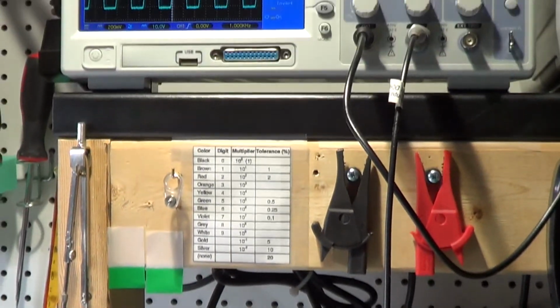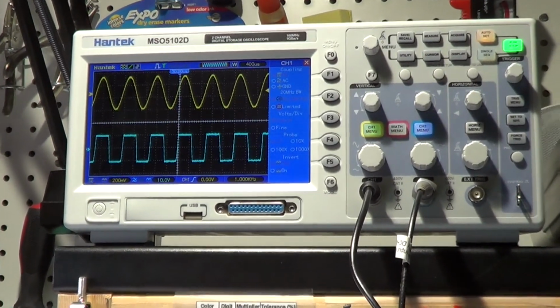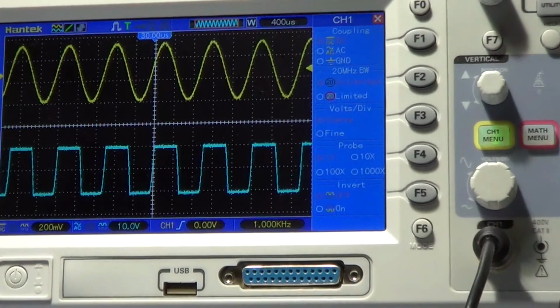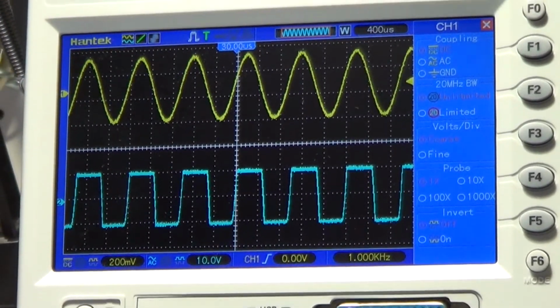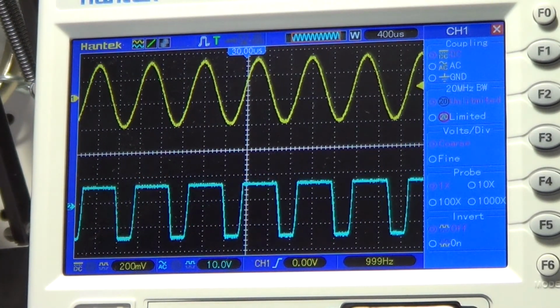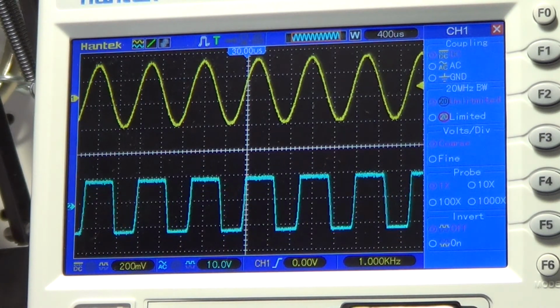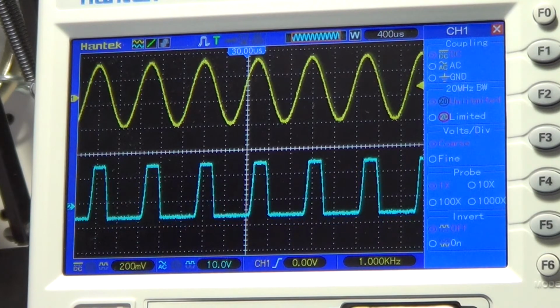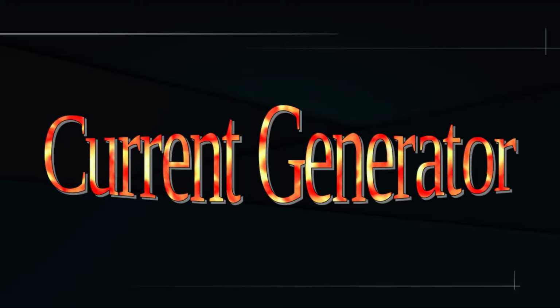You can see that the op-amp jumps from positive to negative voltage depending on the level of the input signal. And since I have the reference voltage to 0, the output goes high on the positive part of the sine wave and negative otherwise. But now, if I change the reference voltage, you can see that the amount of input signal higher than that becomes smaller or higher, and so the length of the ones and zeros of the output signal changes accordingly.